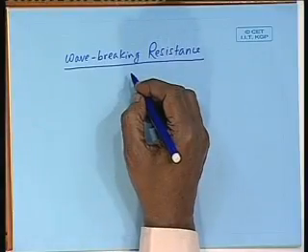Okay. Now, we talked about form resistance, and we said that the form resistance is primarily the 3-dimensional form resistance, 3-dimensional effect on friction. But we have got these other components of viscous resistance now, viscous pressure resistance, and we have got wave breaking resistance. How do we take this into account? We take all this into account in something called form resistance. Do you understand me? Now, let us say there is a little gray area here. I want to make it clear that there is a gray area.